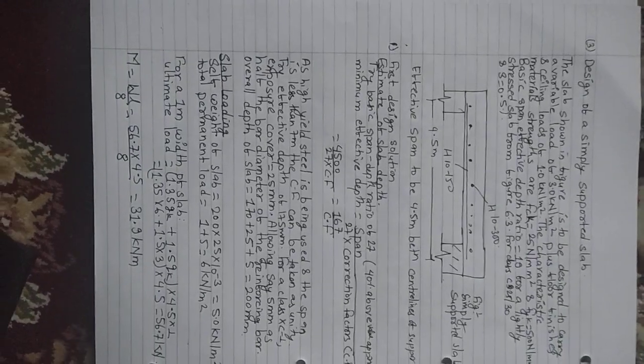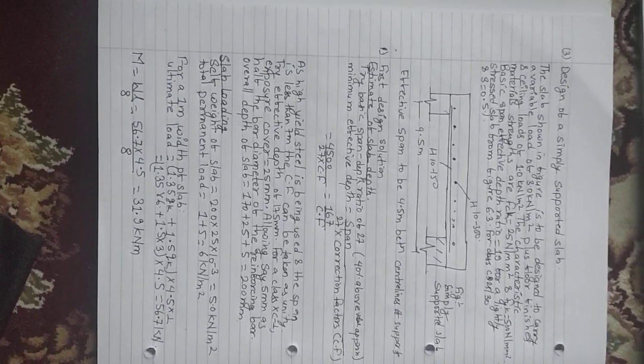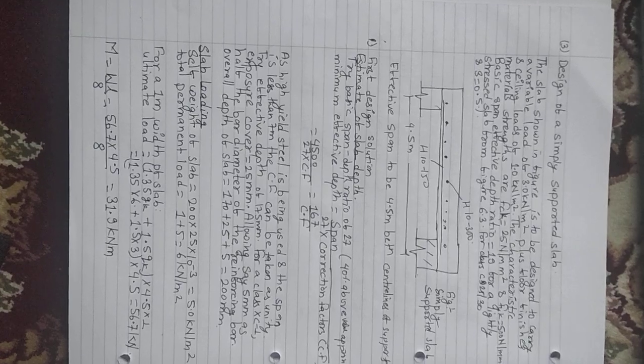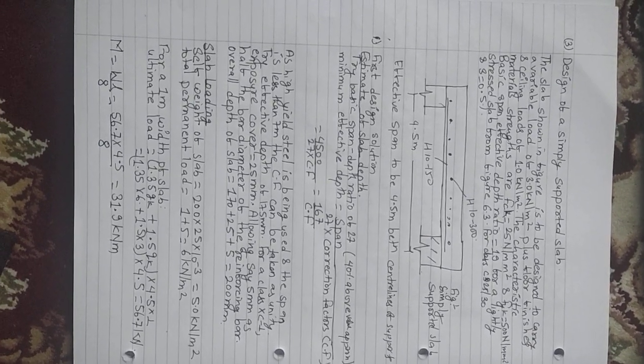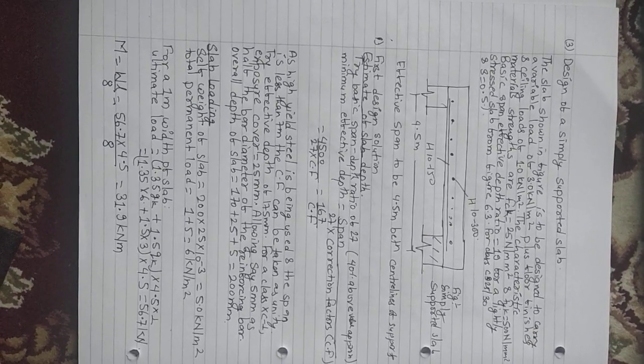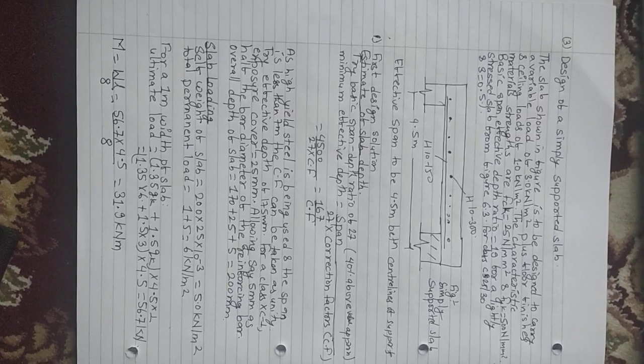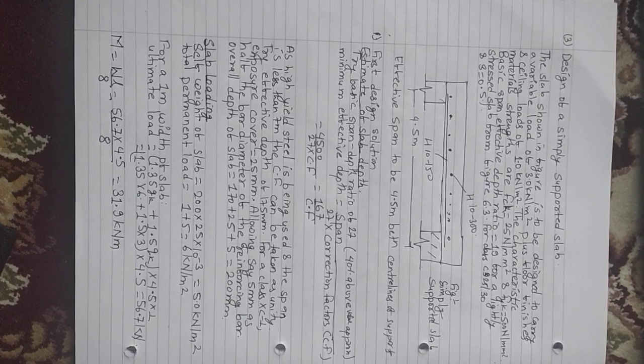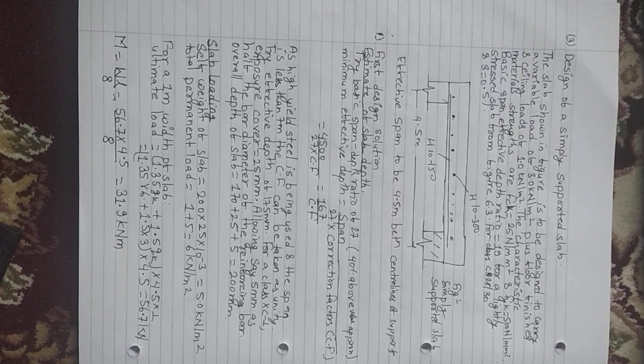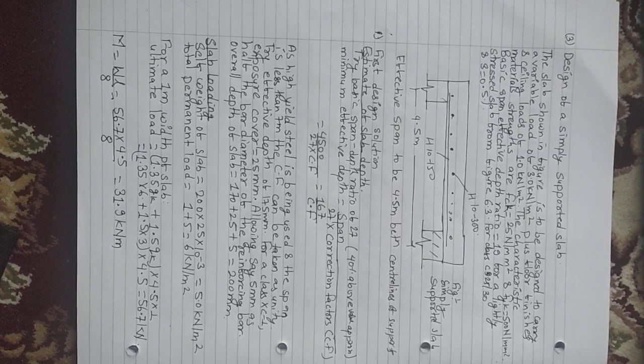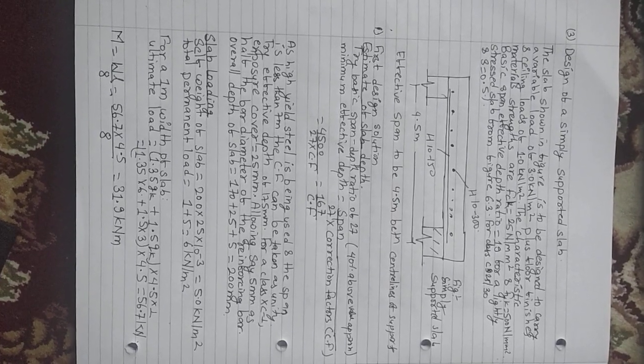This is the next example. Let's design a simply supported slab. The slab shown in the figure is to be designed to carry a variable load of 3 kN per meter square plus a finished ceiling load of 1 kN per meter square. The characteristic strength of concrete is 25 kN